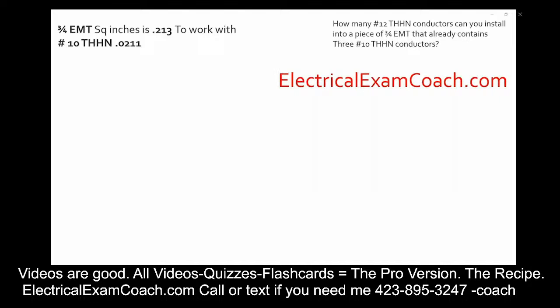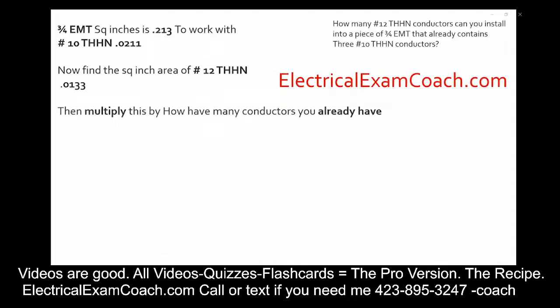Now that we have our conduit and our starting conductor, let's go ahead and write down our number 12s. That's the conductor that we're wanting to install. And then we'll be done with the code book, and all we have to do is some simple math. After we find that value and write it down, we can proceed. We're going to multiply our conductors that we already have. We have 3 number 10s multiplied by the value of a number 10, and that gives us this number.